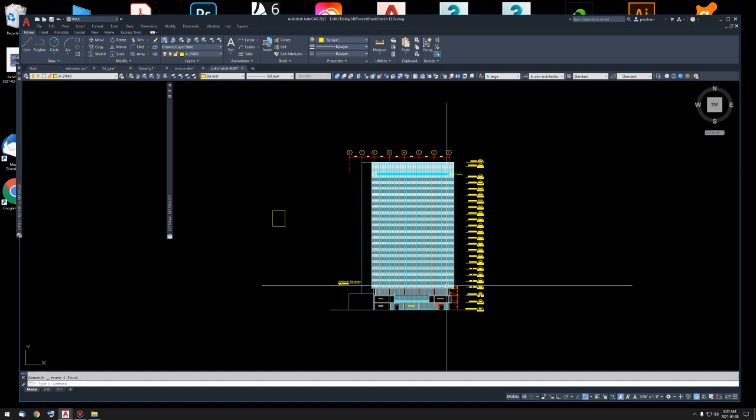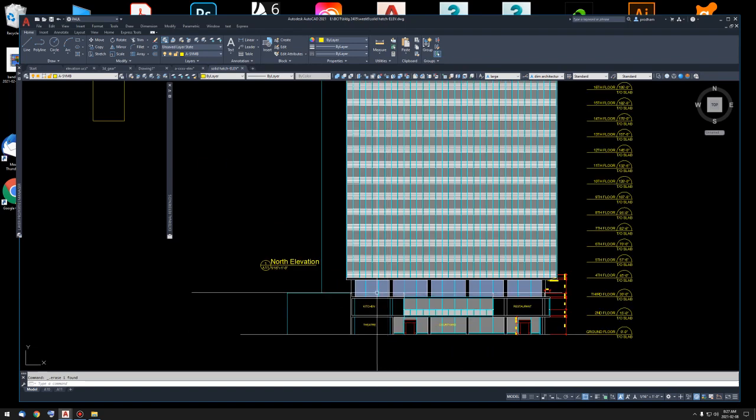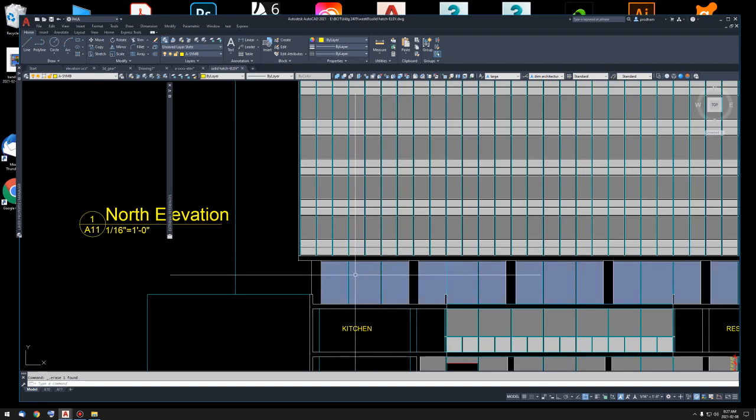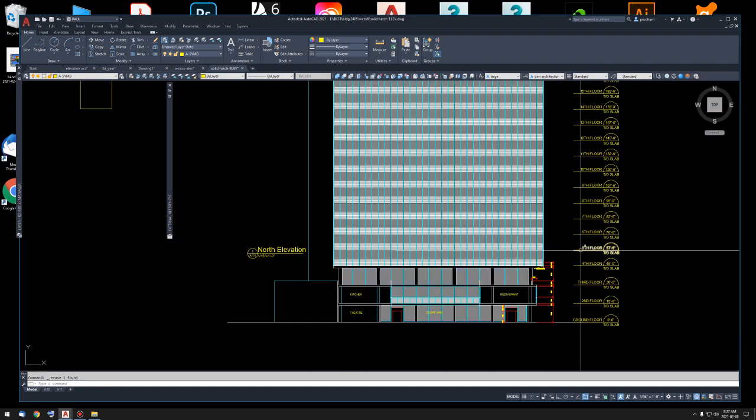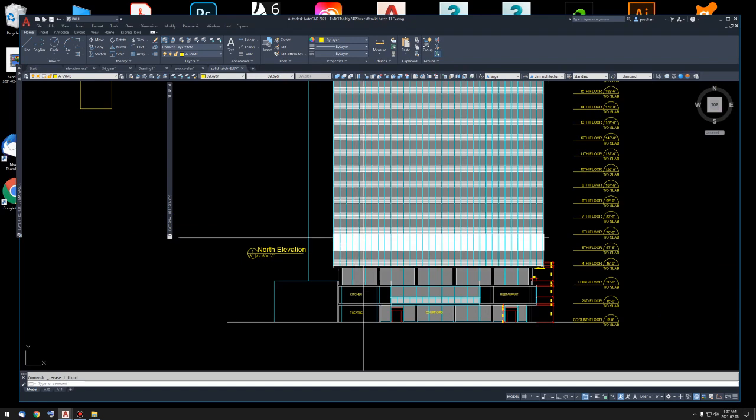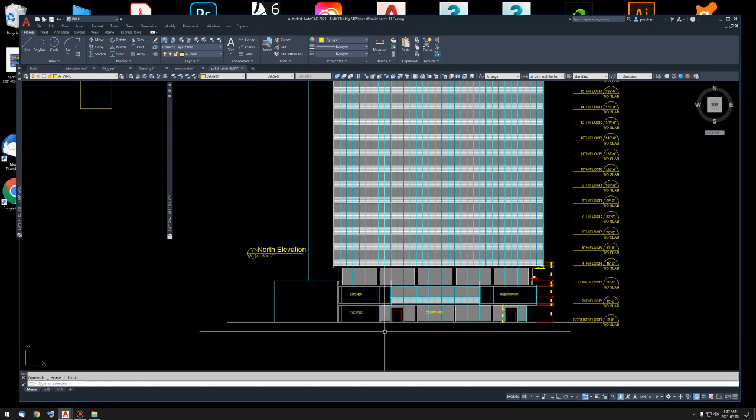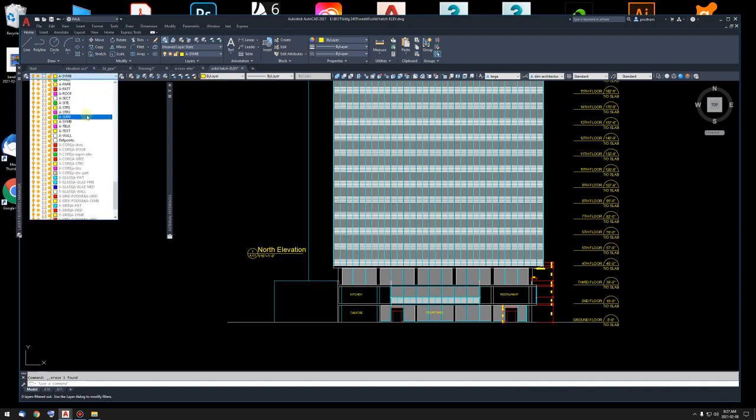I think that's probably the best I can do. There should be a lot of questions where people will have problems with little things to do with annotated scale, I'm sure. Oh, and layers, I'm sorry, with layers. Make sure you understand line weight based layers in elevation, not object based layers. So these aren't on the wall layer. These aren't on the glass layer. They're on line weight layers. Hopefully this person got it right.